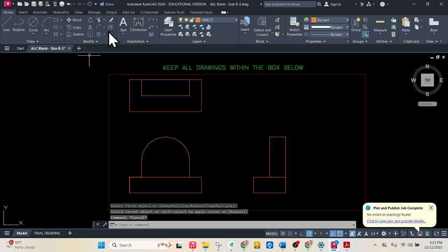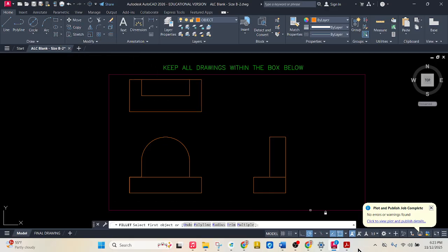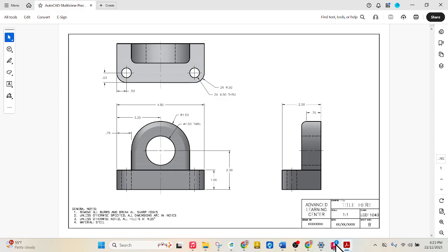While I've got my fillet tool going, I'm going to get the edges here and there. I think those are the only spots. Yep, just right here and right here. This one right here is 0.5, so these large ones are 0.5, and the smaller ones here aren't indicated, but it says down here in the general notes that it's 0.25.